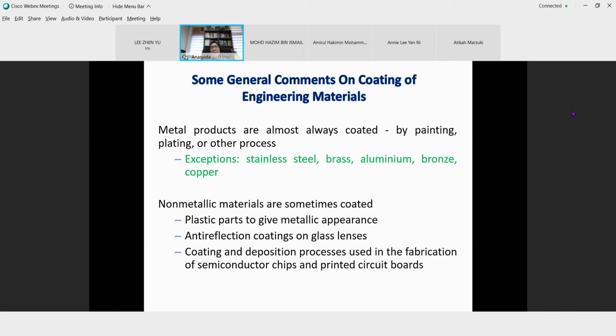There is no coating or painting on the aluminium, because aluminium is able to react with oxygen in the air, forming aluminium oxide, which is ceramic, on top of the aluminium. This forms a very hard protective surface that protects the aluminium from further corrosion. This is the nature of the material.